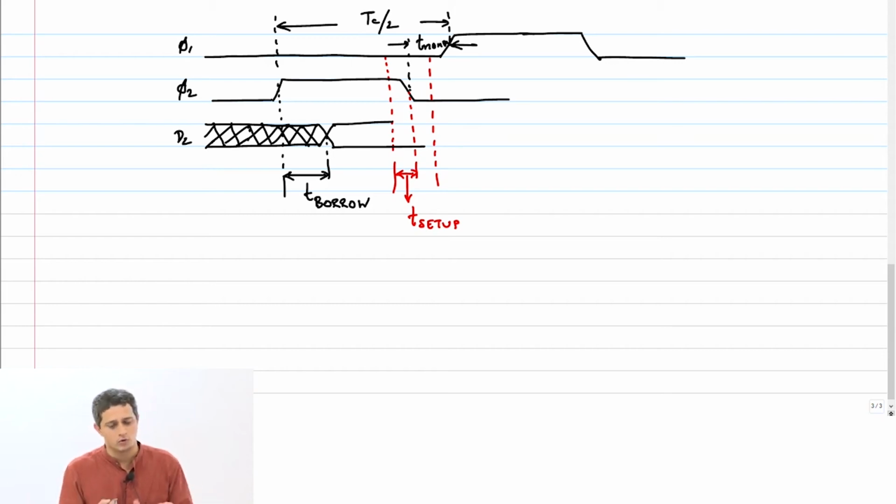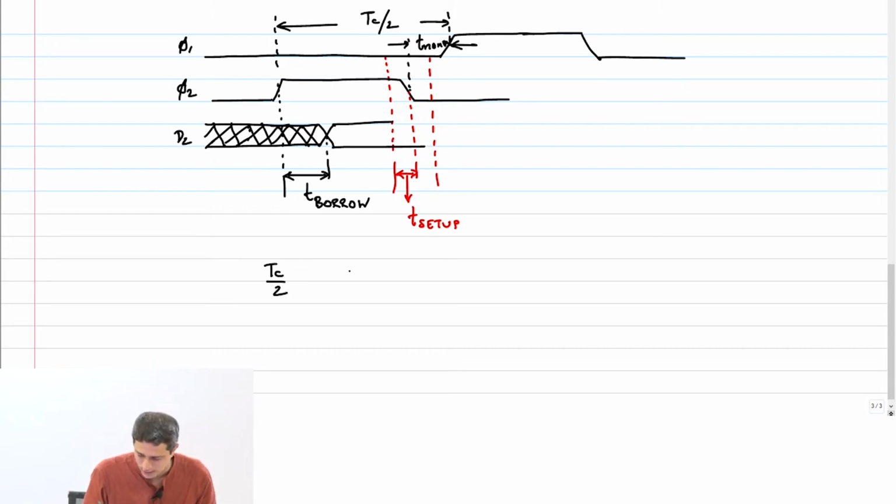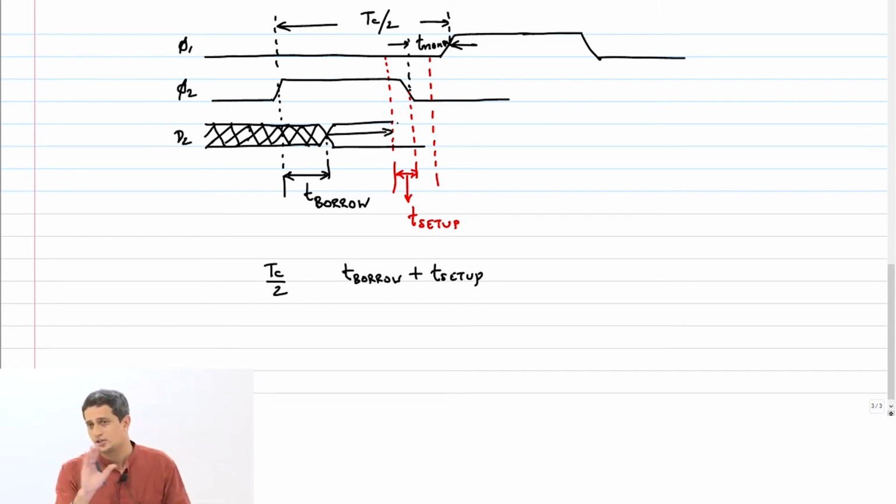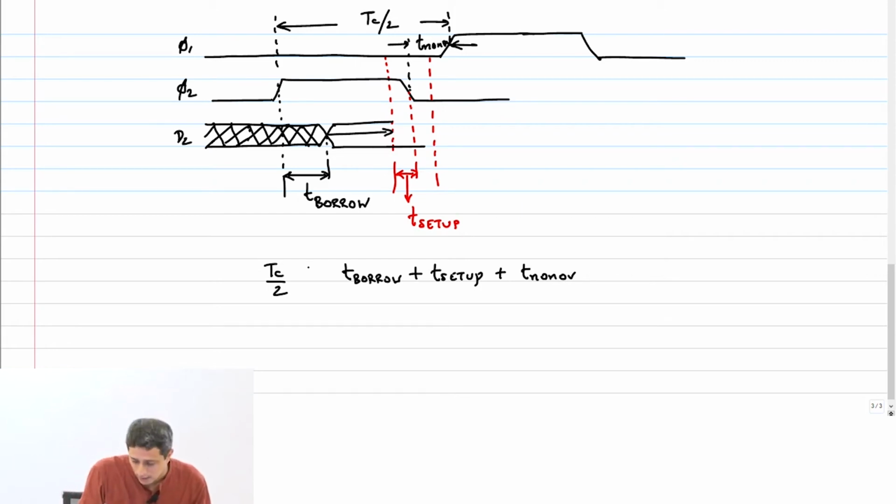So now you simply add all these components. I have Tc by 2 on one side. I have T borrow plus T setup. Because this edge can move all the way till here. There will be no violation even then. So in the limit, it is T borrow plus T setup plus T non-overlap. What's the inequality? Greater than or equal to, which implies...